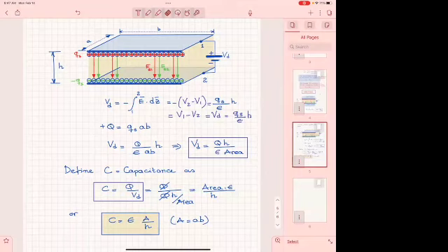We would like to see what happens if we apply a voltage to one side, but we leave the other disconnected. What's going to happen to that capacitance? Is it going to be the same, or different? These are very practical problems that you see in circuit design. If you don't ground one side of the capacitor, then it's not performing for you because it gives you something different. It's not the capacitance that we calculate from here. Or if you have capacitors one next to the other, or in parallel. How did we get the formulas for series and parallel capacitances from here? Nobody told you that, but in reality, that's how you got the formulas that we used in circuit design.